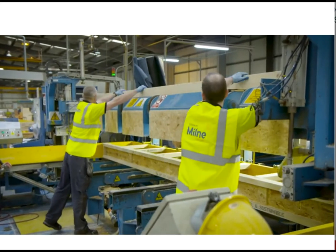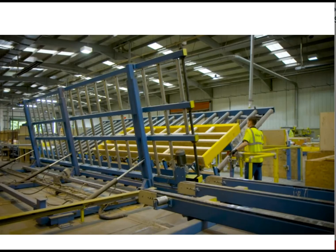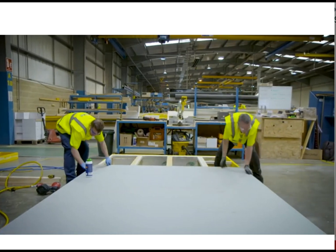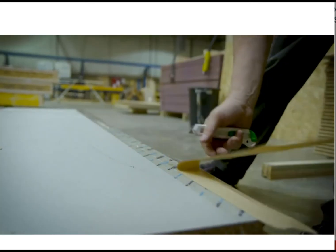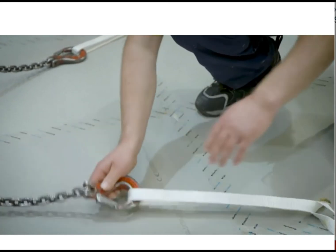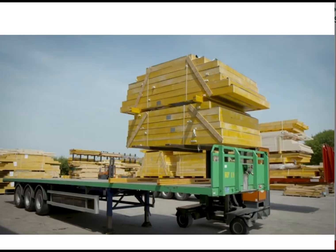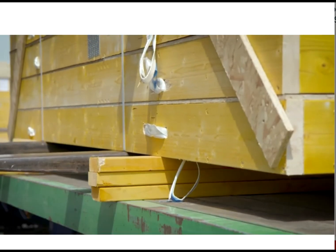The timber floor components are all pre-cut, assembled to form cassettes, and then flipped over. Chipboard finished flooring is used to deck the panels, and all joints and screws are covered with a protective tape. Integrated lifting slings are incorporated so they can be easily manoeuvred and dropped into position on site. Finally, the advanced timber frame panels are lifted onto the transporter and taken to Arborfield.